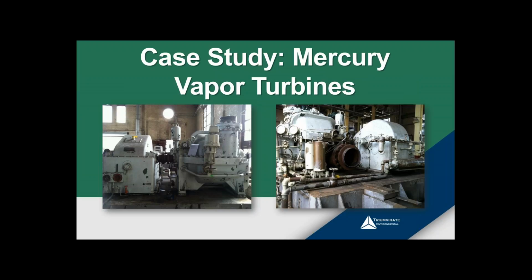So this is a mercury vapor turbine. A mercury vapor turbine is a form of heat engine that uses mercury to drive the thermal cycle. Mercury vapor turbines have been used in conjunction with steam turbines to generate electricity. The mercury cycle offered an efficiency increase because the complete cycle can be worked over a very wide range of temperatures without employing any abnormal pressure.